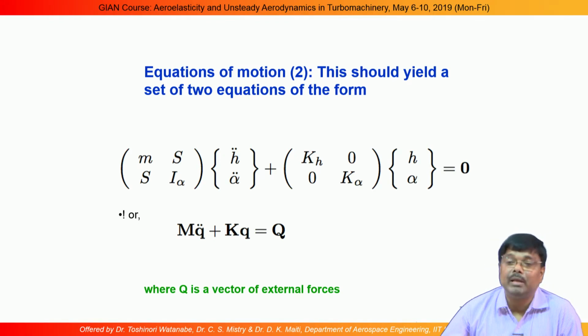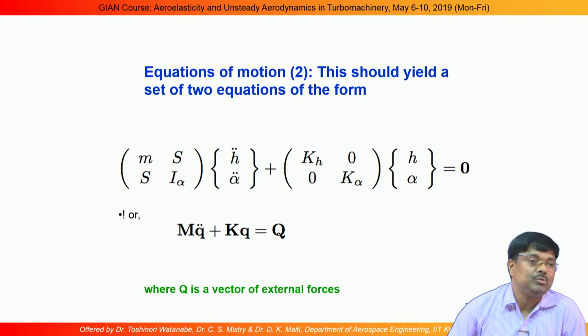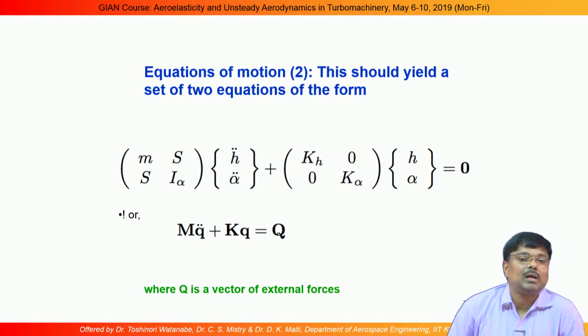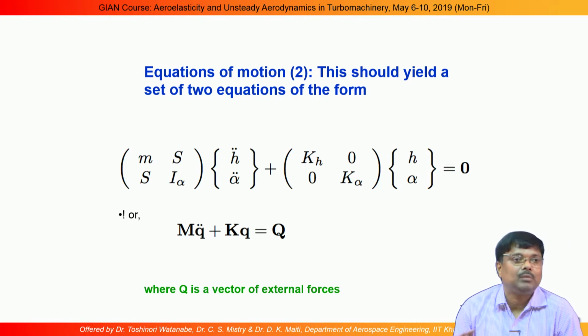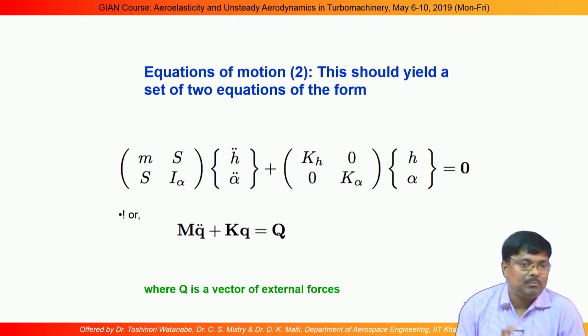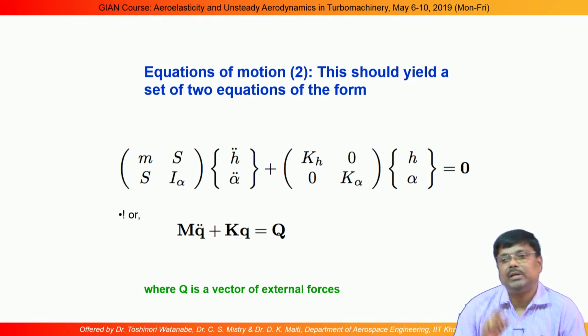If I take damping, then what will happen? The frequencies I will be extracting are complex numbers. The mode shapes I will be extracting are also complex numbers. So, there we have to consider the eigenvalues, we have to take the real and imaginary part for finding the damped natural frequency, and for the modal vector I have to take the absolute value to find the actual amplitude.